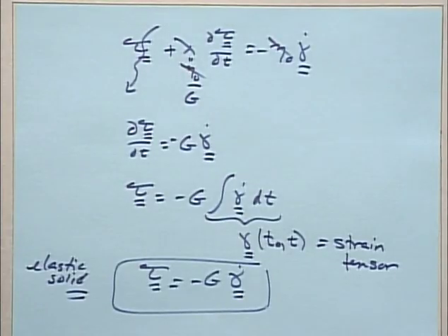Exactly what we saw with silly putty. Okay? At very low rates, when you sit it on the table and let gravity take over, it flows like a Newtonian fluid. And when you bounce it, it bounces like a rubber ball. Okay? So it's a reasonable model. Next time, I'll show you that it's the same as the other one.